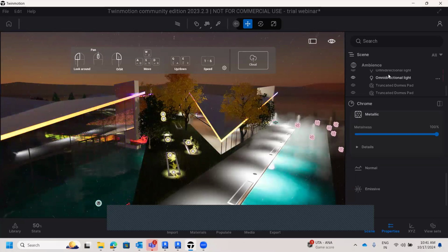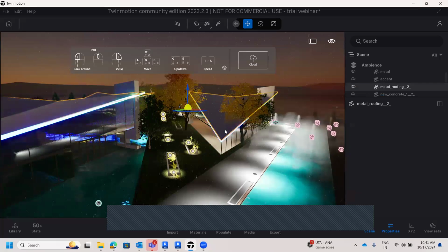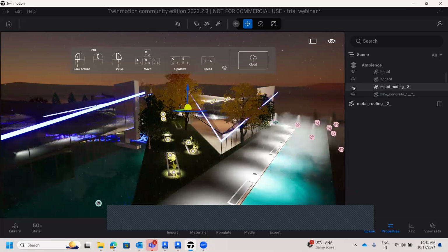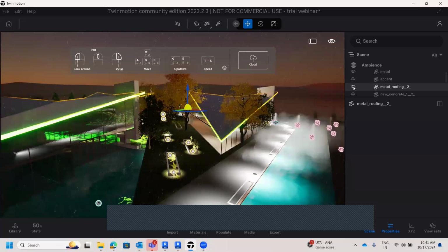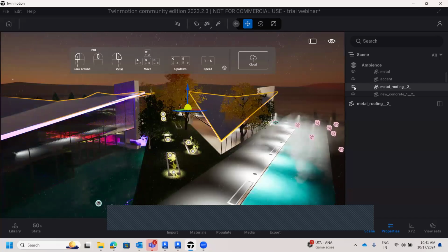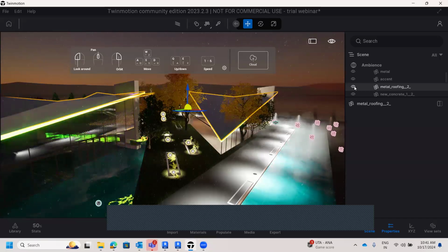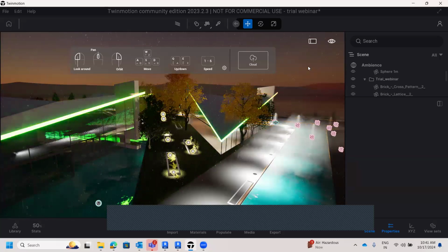So you can see here, if I click on this particular surface, this is metal roofing. This is the layer. If I switch it off, you can manage those layers accordingly within this platform, on and off. Likewise, this is quite helpful in utilization of entire building assets, to manage the building assets for visualization purposes only. Right. So these are the layer aspects where you can get all those things.